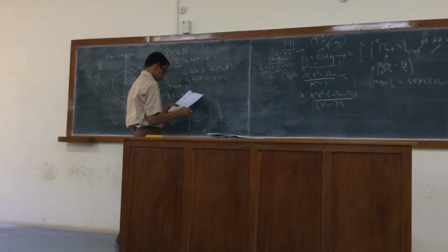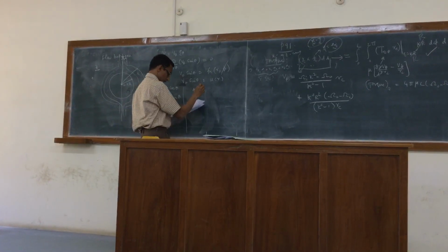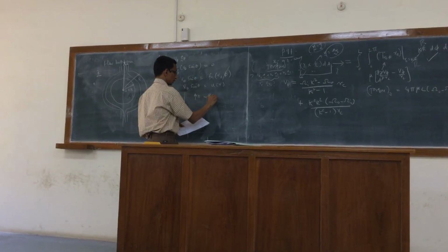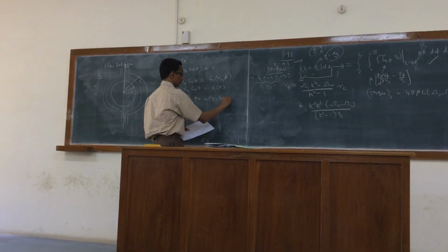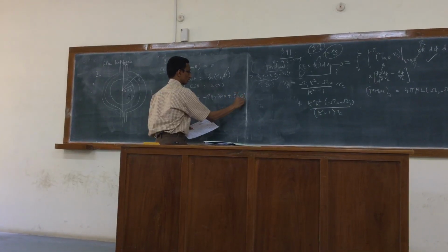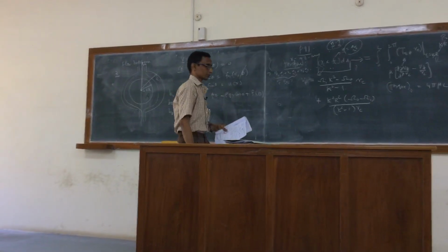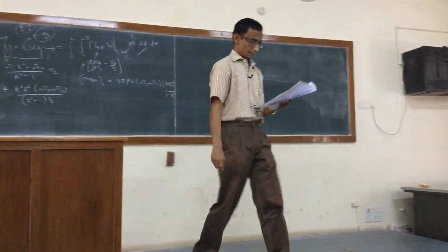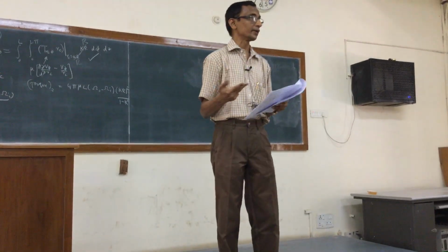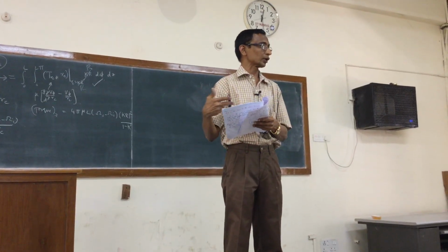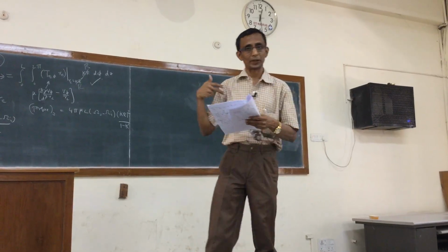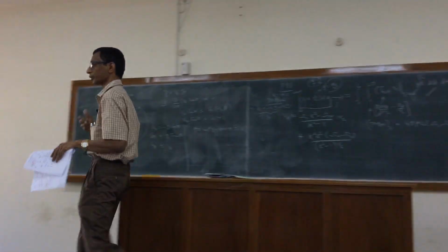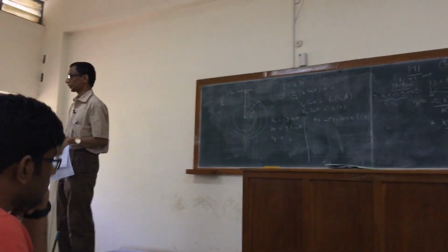And so if you substitute this into the equation of motion, you will get that the pressure is minus rho g r cos theta plus some function of theta. Here, in fact, the equation of motion tells you that you don't have to neglect dp by d phi, because it automatically turns out to be 0, since the body force component in the phi direction is 0.